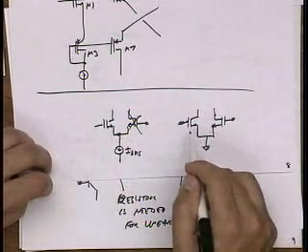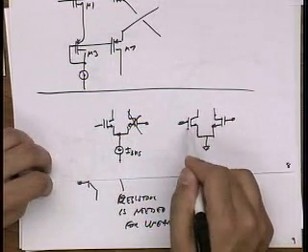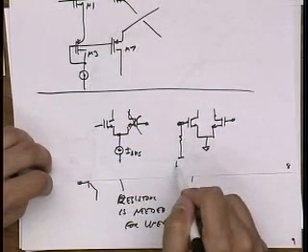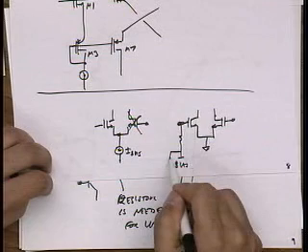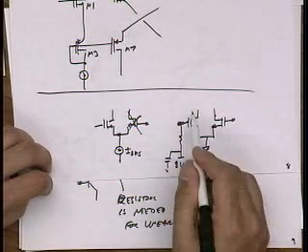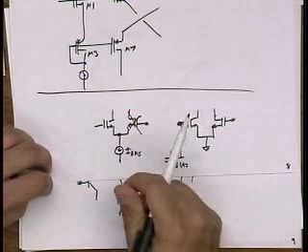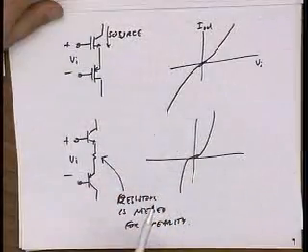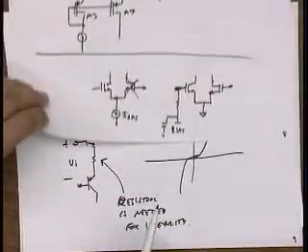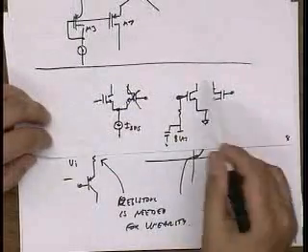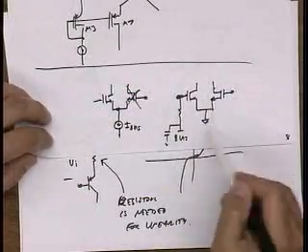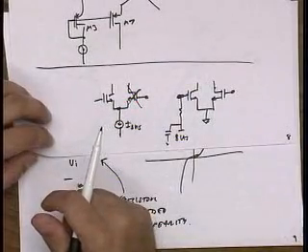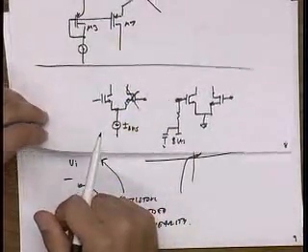So it's not quite the same, because in this circuit I have to tie this to some bias, right? And there is a time constant associated with establishing this bias current. It's not quite the same, but it is a similar effect. Incidentally, as supply voltages have gone down, using the pseudo-differential topology has become a lot more popular. We just don't have the headroom to give up to the current source.